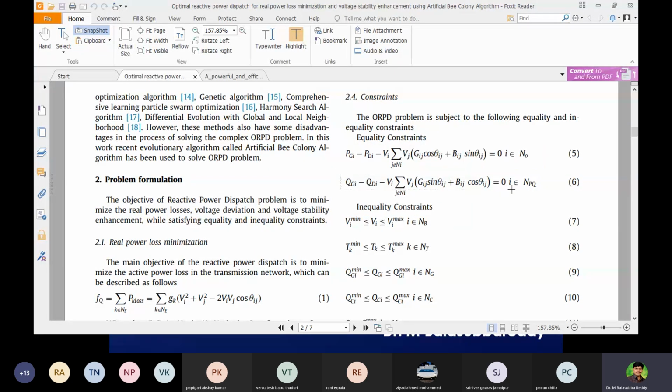Whether it is real power or reactive power, you can see this statement in the equation itself. You can come to know that PGi is the generation of any generator, whether it is generator 1 or generator 2 or whatever you call it. In that particular generator, PG means generation, D means demand. Now if you move this to the right-hand side, you get PDi plus this term. What is this minus sign term in the equation? It is nothing but the loss equation.